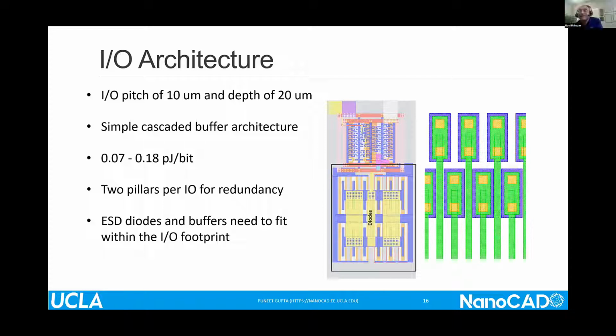Got it. And then there's a very practical question: how did you implement the 20 nanofarad on-chip cap? Is it MIM, or are there any special materials? How much area does this take? There are no special materials. Unfortunately, we were stuck with whatever the process provided. There's absolutely no special materials. That's why that area is so large. I mean, 30% of the die area being just decap. You can imagine how we hit it.